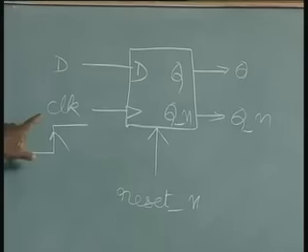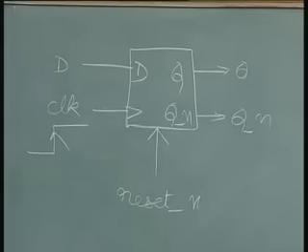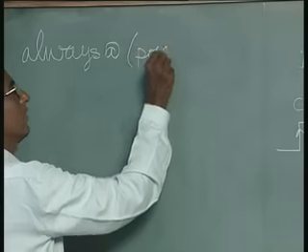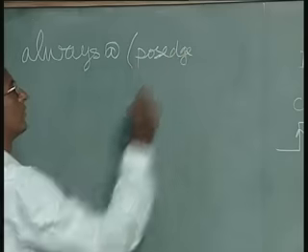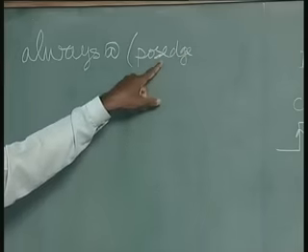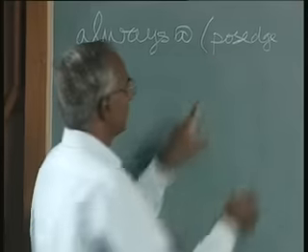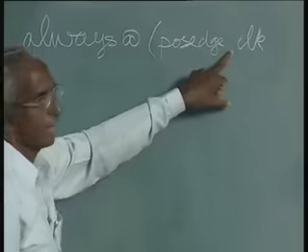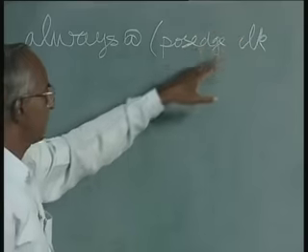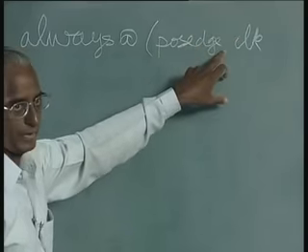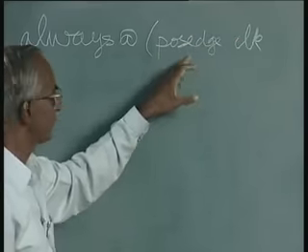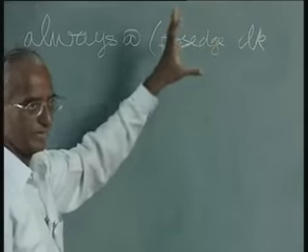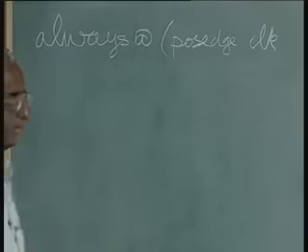For example, you want this at positive edge. So what we do is we use a reserved term in Verilog called posedge. Note this. If you make a spelling mistake, naturally the tool will complain. So now we give a blank, one or more blanks. At least one is mandatory, otherwise the tool cannot distinguish between this and this, and do not put an underscore or any other symbol, just a plain blank as such.